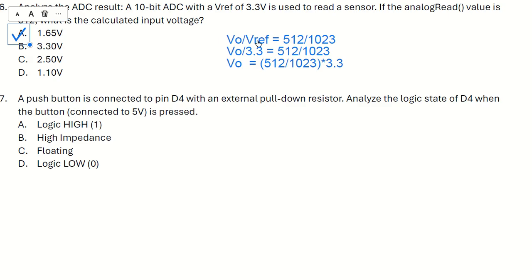Okay, so that means the question can ask you anything. Maybe ask you what's the V reference, what's our example in module 2.4. 2.4 is about the ADC output. So if they tell you 1.65 volt was measured, what is the digital ADC value? It will be 512. So that's why you need to totally understand what you are doing.